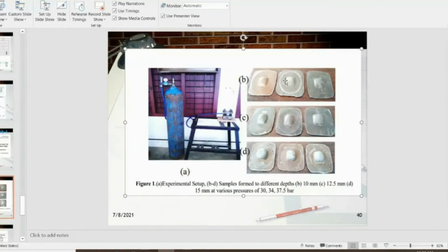There is some logic here, but I don't want to explain that. The thinning will happen. That is inevitable in superplastic forming. There are so many techniques to reduce this thickness variation. You cannot expect the same thickness throughout the component. The thickness will be more here, and thinning will be at the last portion, where it is forming last. That will be more thinning. So we calculated the thinning ratio. There are two important things we are interested in.